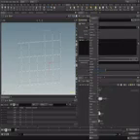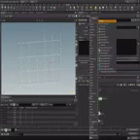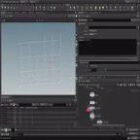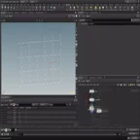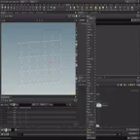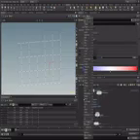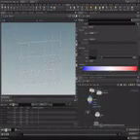A way to remove that line is because we know each segment has, well, right now we don't really have a segment, so let's first place down a convert line. That was one node I forgot. So between the fuse and the primitive wrangle, let's place down a convert line. And then if we place down a measure node and wire that over there, we're going to set it to perimeter, and then a delete node. And the delete node is going to delete everything which is too long.